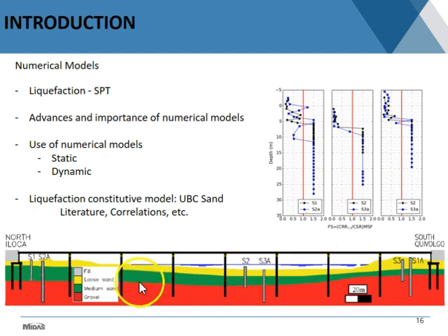The non-liquefiable ones, we just modeled them using a Mohr-Coulomb, elastoplastic kind of modeling. In this case, since we didn't expect to see too much failure or deformation in these soils, it proved to be a reasonable assumption. If you have a combination, maybe you want to try to use something a little bit different.